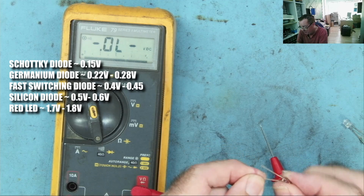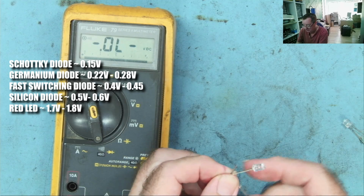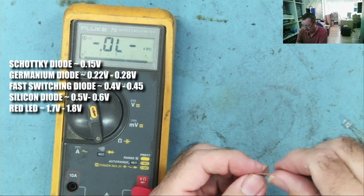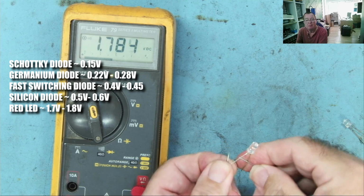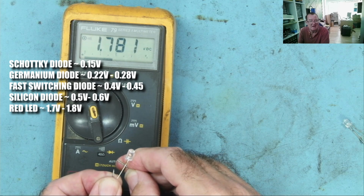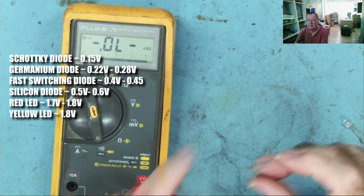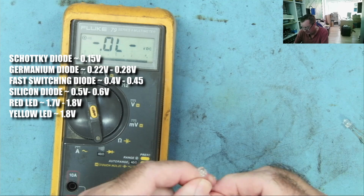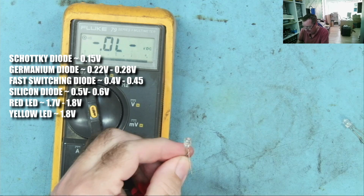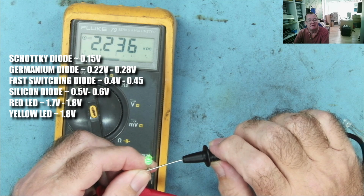Here we have a yellow LED. Same thing, it will light up in one direction with the positive lead or the red lead to the cathode. You see that's not lighting up, it's not conducting. And that's a yellow one, so you can see it lighting up there, yellow against the background. And that's reading about the same as the red, 1.78. Here we have a green one. Let's try again. So clearly lighting up, and we can see the voltage drop is higher on this one,